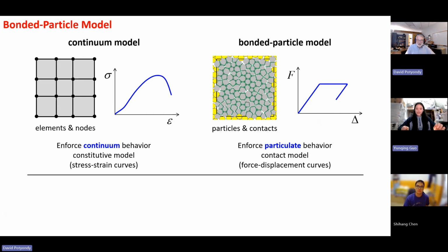When they push together, a little overlap forms, and a force builds up, equal and opposite, pushing against them. So this is the idealization. It would be like grains of sandstone, that is, quartz grains being pushed together. The grains themselves are really not doing anything. All the action is happening at the interfaces between the grains. That's where all the deformation is happening.